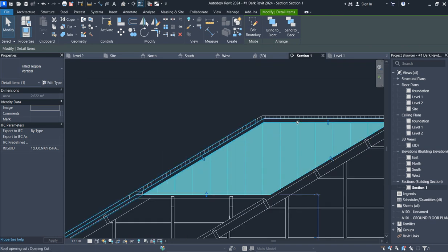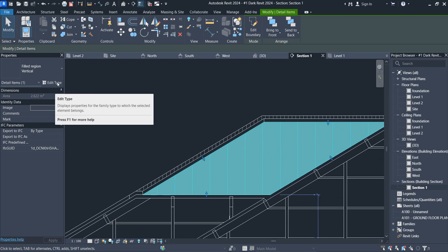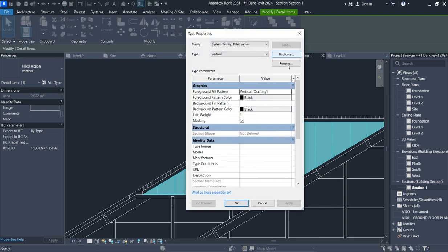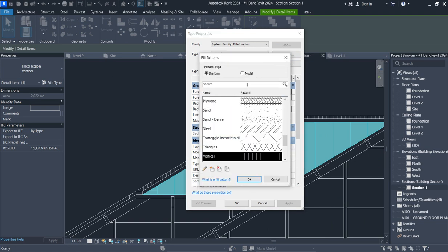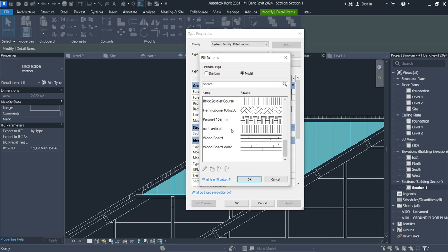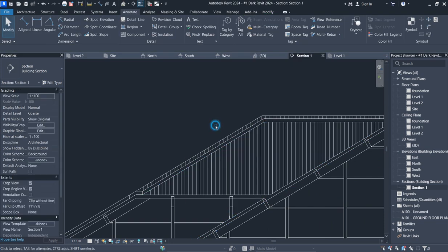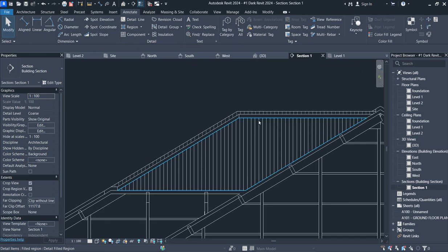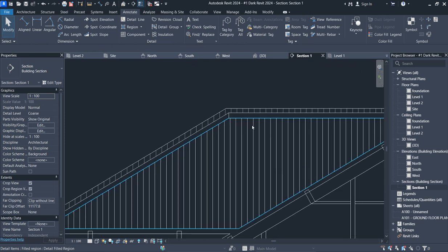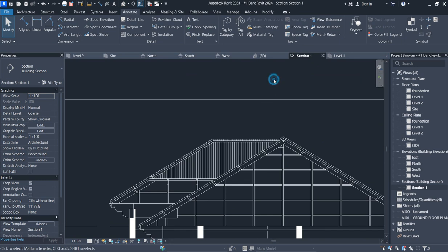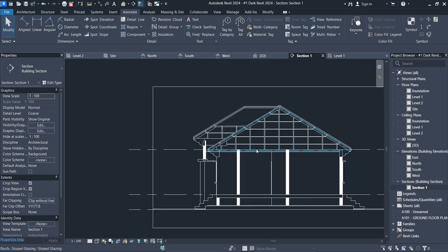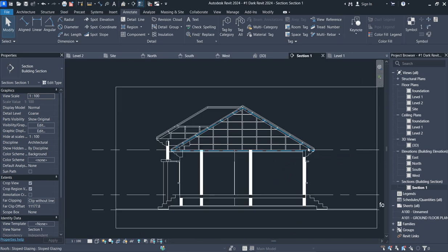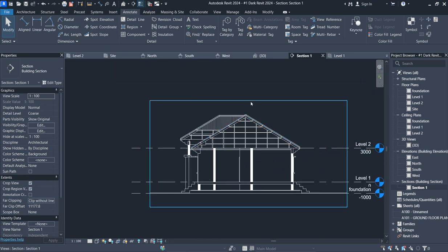So what you do is that you have already vertical spaces that you need, but you need to make sure that they match with this reference line. So how do you do that? Say click here and say foreground pattern. So click on model in place. Model in place now. Roof vertical is what you choose, and say okay and say okay. So can you see? Because they have the same, the references are matched together. So that is how you create the roof pattern in this place.